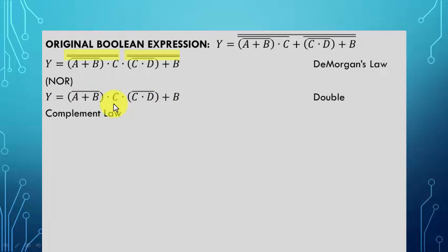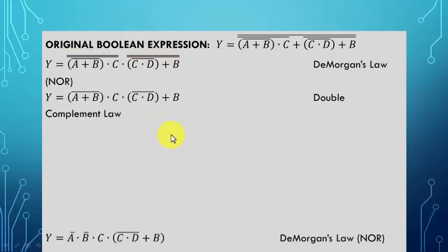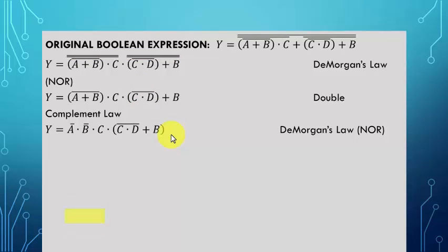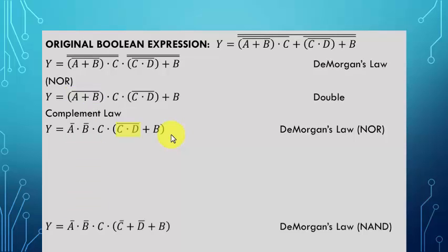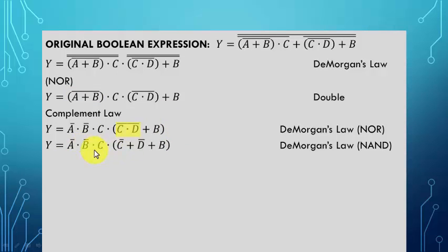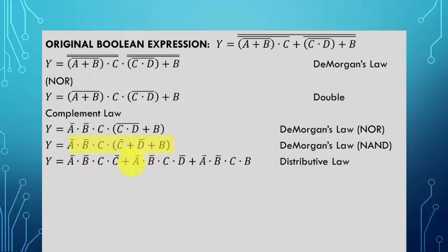And then we can continue to use the De Morgan's law. So over here, you can break the line, change the sign. Same thing over here, break the line, change the sign. Break the line, change the sign. Then, after you get to here, consider to use the distributive law. Then that expression will become the OR of three multiplications.